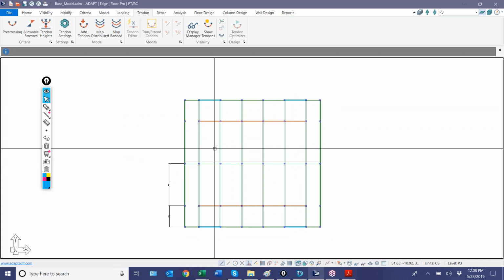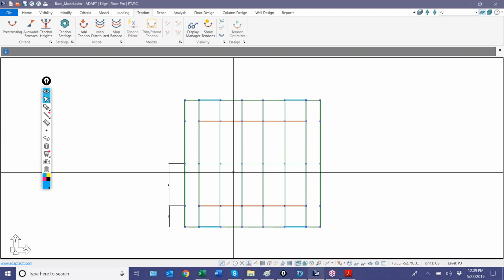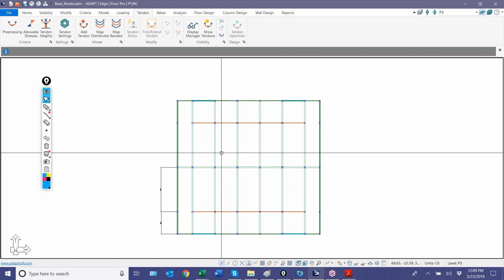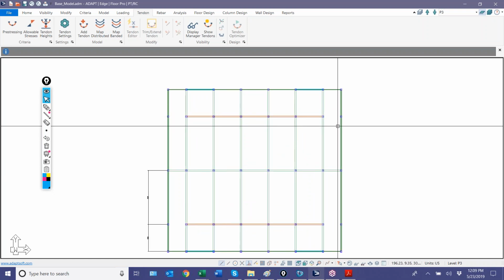So we'll say if we take 456 kips, which is our requirement to meet minimum P over A, we divide that by 26.7. We need 18 strands in each interior beam. So I'm going to model 18 strands.